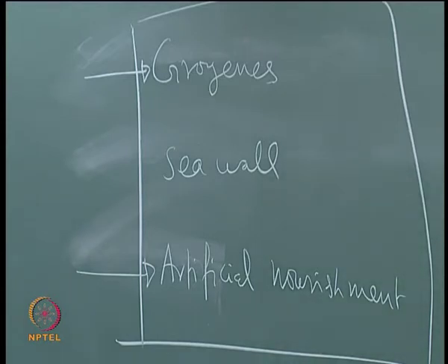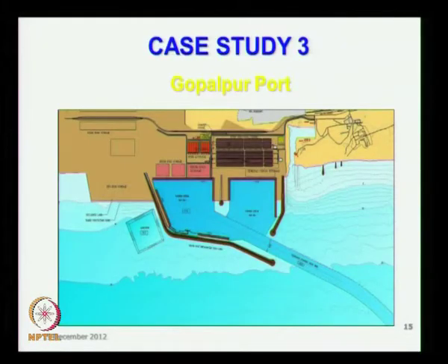This is on the east coast, between the Andhra and Orissa border, in the Orissa state. This is the southern breakwater, which is about 2.5 km long. Now they are building this intermediate breakwater, called the north breakwater. There is already a coastal inlet inside, they have two breakwaters here, and these are the groins which are schematically shown, but the detailed design has been carried out recently.